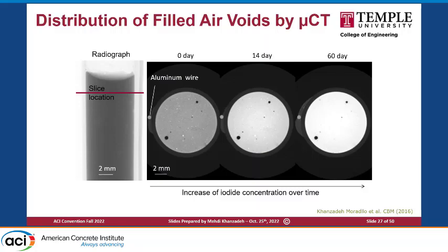And the other perspective here for freeze-thaw is the air void filling by the salts, or if you are having a salt deposit inside the pores, how that's going to impact your overall freeze-thaw performance. So in this case, we can use X-ray imaging. I discussed the background about X-ray tomography.